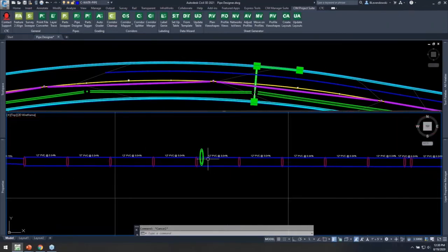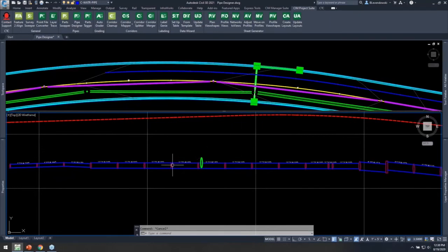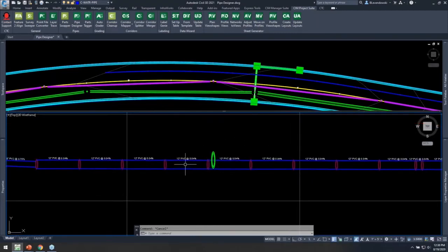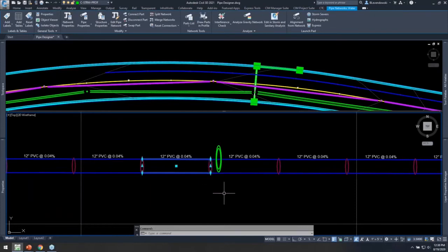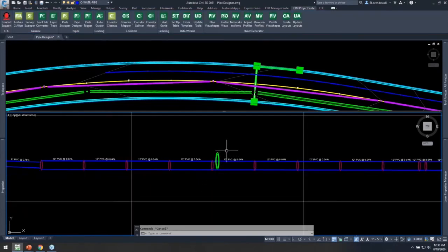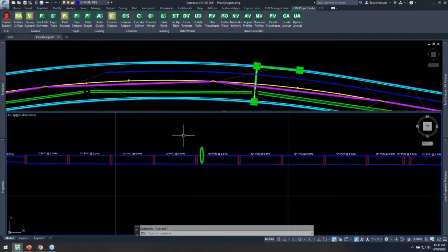And you can see it's violating, right? We've got that storm, the water main is in the way. We can't move the storm, so the water main needs to go around it. We can't go above it, we need to go below so we maintain that minimum cover. And normally you'd be kind of grabbing these pipes and manipulating them, but it gets really kind of tricky to work with because, do you need to put in a 45-degree bend? Can you just angle the joints a little bit so long as you don't violate your deflection? It depends on how much you need to slope this stuff and what you're doing.